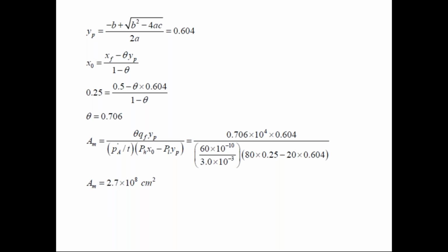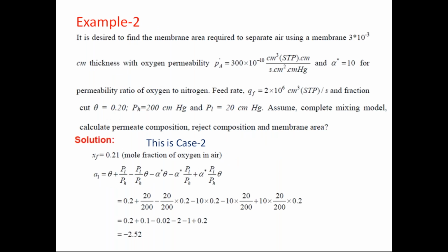You cannot utilize all the area which is there in the chemical process plant for the membrane unit. So you have to reduce, a very compact membrane unit has to be used. So you can select the configuration, spiral wound, or plate and frame, anyone which is giving you this much area, and also making a good contact and withstanding the pressures which you impose over that. Okay, and similarly this is another problem.